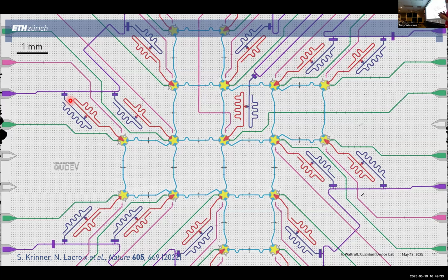So this whole chip is cooled to the lowest temperature that your dilution refrigerator can achieve. That's usually around 10 millikelvin or so, 10 thousandths of a degree. All the components on the chip are superconducting. So when you apply all of these control pulses, the actual loss on the chip is very, very small. The heat that gets generated by applying these fields is quite small. So it doesn't physically heat up a lot in a way that you could actually measure a temperature.